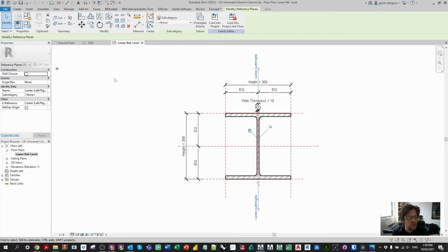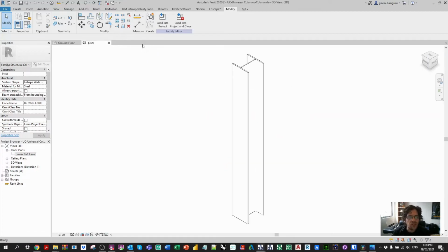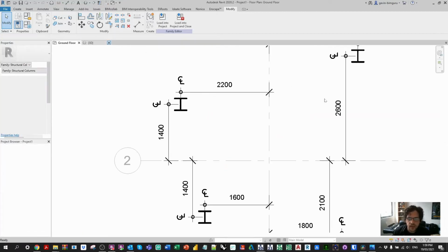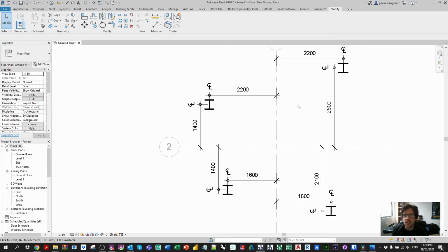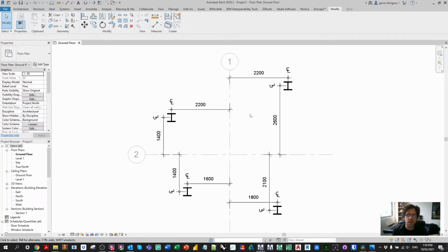So we're going to be working predominantly with the center left right reference plane and also the center front back reference plane of each of these objects in this workflow. The Genius Loci package is going to give us access to a lot of nodes that deal with creating references. Now in this case, I'm just going to dimension one grid intersection relative to all these columns, but you could refer to another one of my videos where I show you how to collect the nearest grids to an element using a different workflow to expand upon this further.